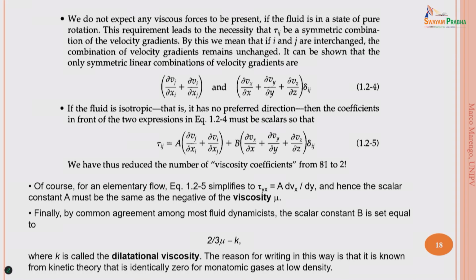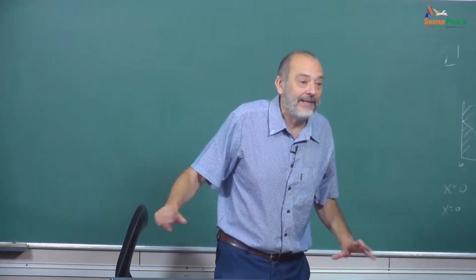Consider that I'm now treating the case of a Newtonian fluid. But in principle, there are non-Newtonian fluids, where we cannot simplify the matrix so easily. So we need to consider also the interplay of stresses in the different directions. Especially, for example, a non-Newtonian, non-isotropic fluid is a big mess. I need to surrender. I'm not a specialist in that. It's really very complex because it's very difficult to simplify the 81 components there.